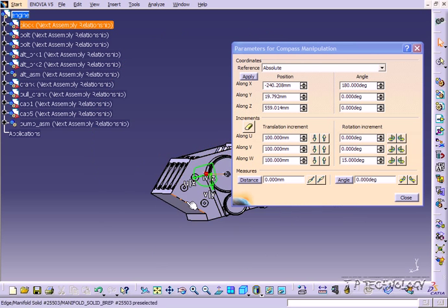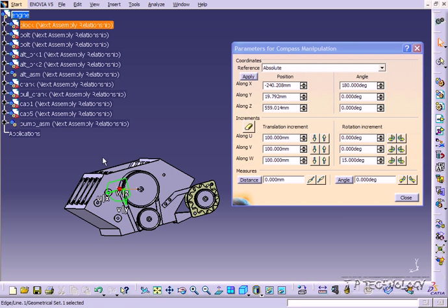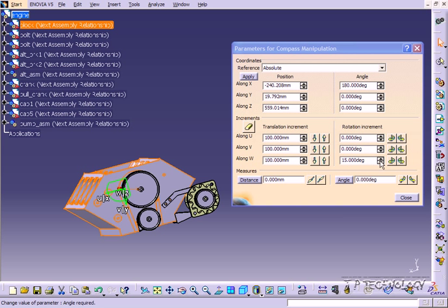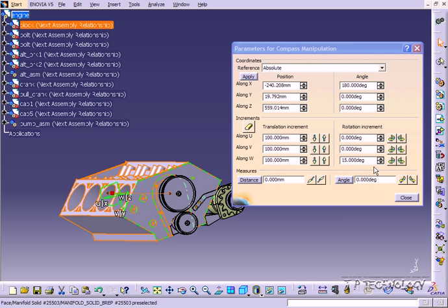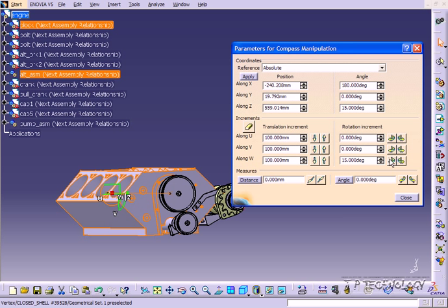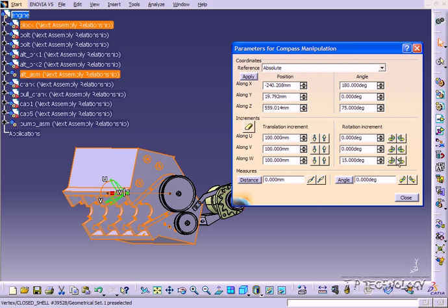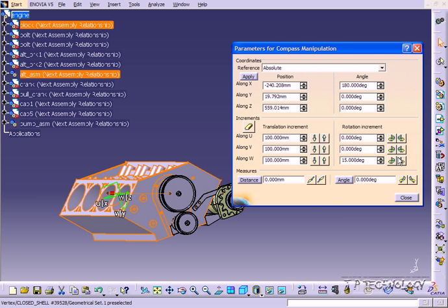So now again, you're able to go through the assembly and use the hierarchy system to pick which parts and assemblies you want to move. To start off, let's move just the engine block. Let's double click engine, just highlight the engine block, and we have it rotating around the W axis at 15 degrees. Let's try it out. You can see how the whole block is rotating 15 degrees every time we click. And again, you can do the same thing if you click on the plane and rotate about it too.